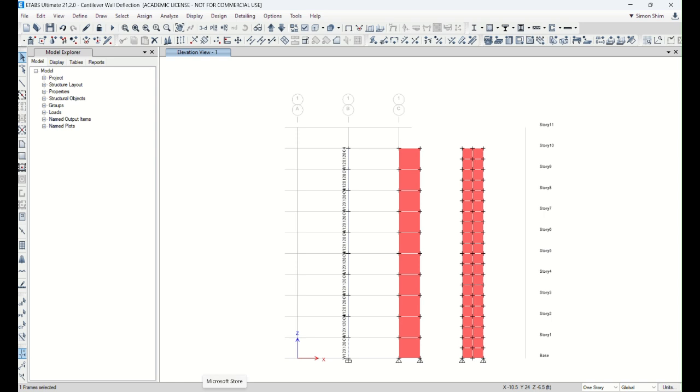There's a difference between our hand calculation and finite element software. But most of them, we need to know all this input, right? Modes, geometry, boundary condition, you should know it. And Young's modulus, right? Moment of inertia, you should know it. So for deflection calculation, you should always have all information for hand calculation and FE analysis calculation. You need to clearly define that. They should be able to, because deflection applies some beam theory, elasticity, the mechanics, so they should calculate the deflection, right, by using the formula.